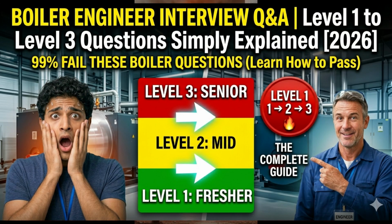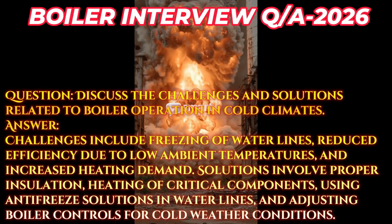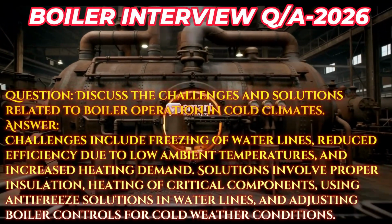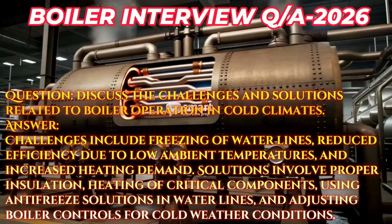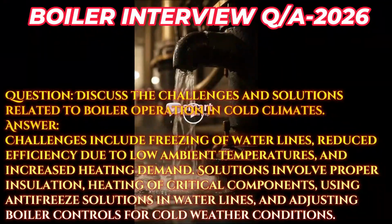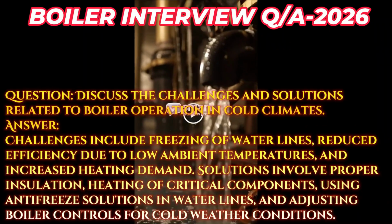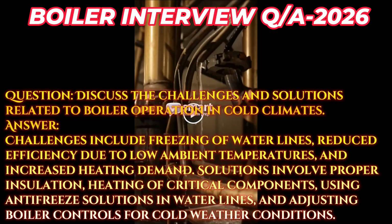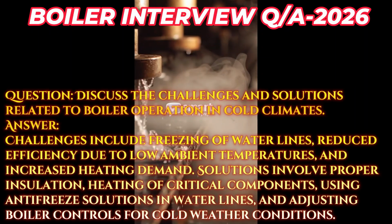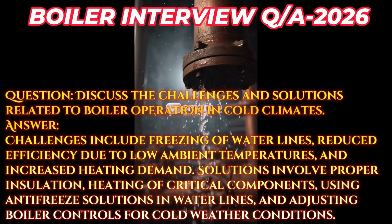Question. Discuss the challenges and solutions related to boiler operation in cold climates. Answer. Challenges include freezing of water lines, reduced efficiency due to low ambient temperatures, and increased heating demand. Solutions involve proper insulation, heating of critical components, using antifreeze solutions in water lines, and adjusting boiler controls for cold